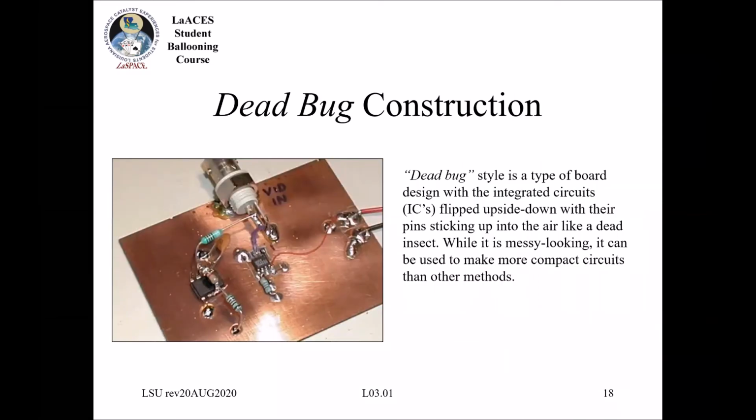And then this is called dead bug construction. Again, something that I haven't really seen too much. The integrated circuits are flipped upside down with their pins sticking up into the air. Oh, interesting. Like a dead insect. While it's messy looking, it can be used to make more compact circuits than other methods.